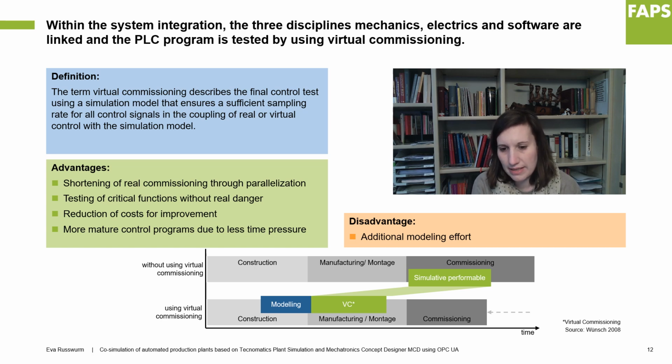At an early stage of the product or development process, simulation by model in the loop can be used. The sequential control is inserted directly into the physical model, and everything is tested within the model. This is more of a process-accompanying simulation, since individual steps are successively taken over by the control system. At this point, however, the physical plant model is already used, which is also used in the other two forms of virtual commissioning.